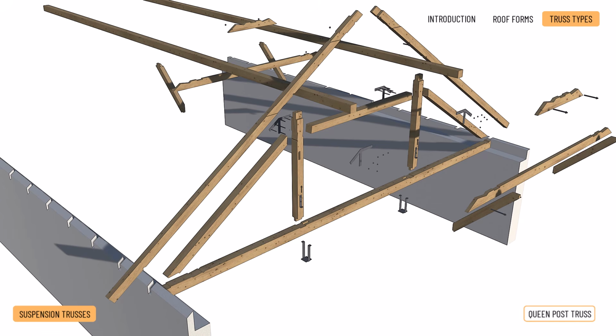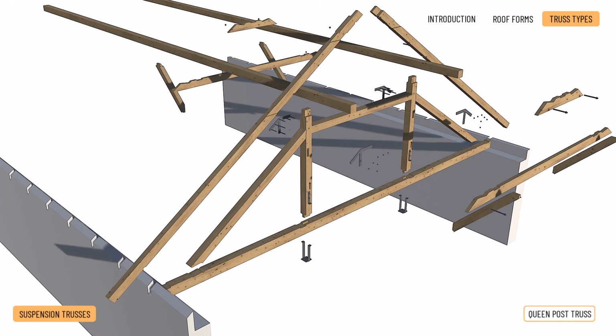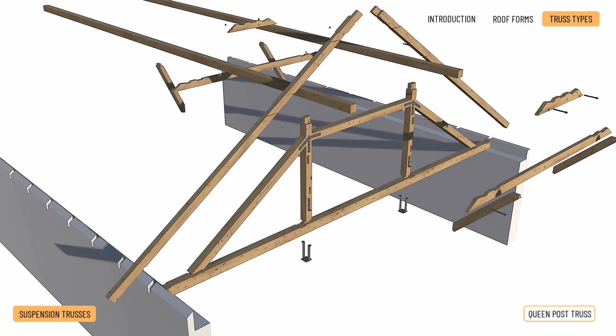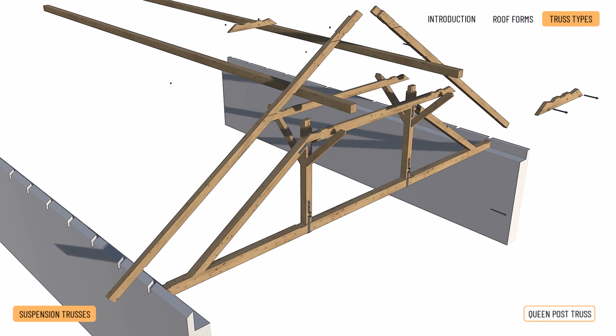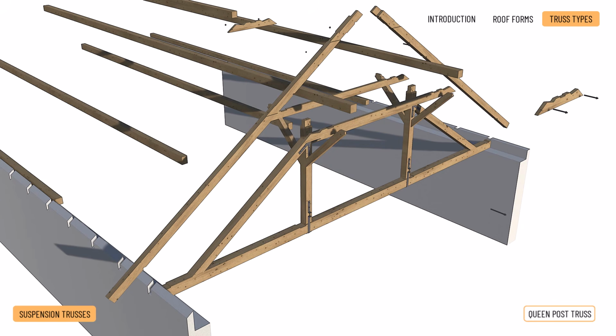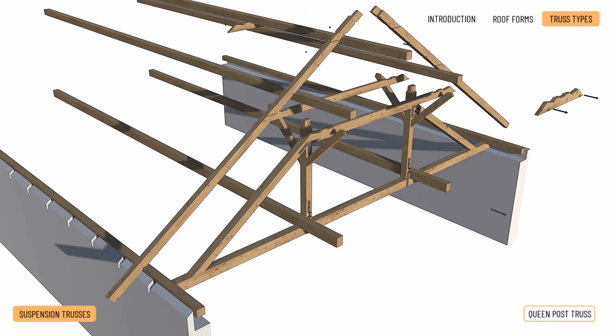The straining beams and the suspension posts are connected with shouldered tenon joints, while the inclined struts connect to the tie beams and suspension posts using double-notched housing joints. When doubling posts, the principal joists are doubled also, and purlin connections are stiffened with knee braces at the principal trusses.